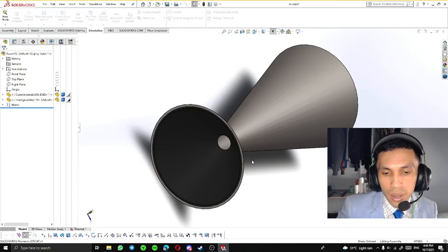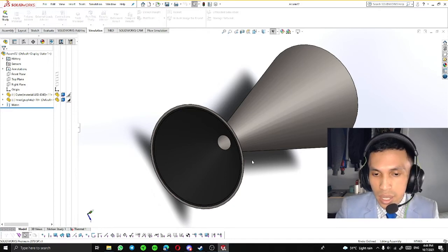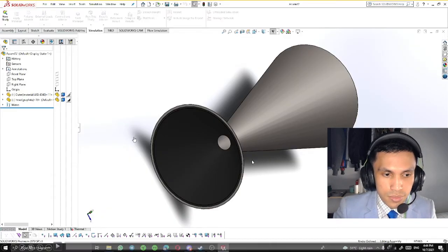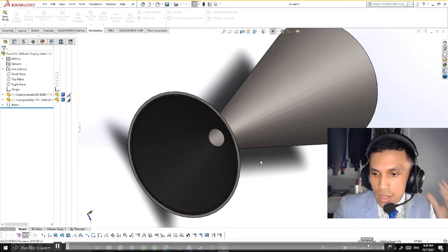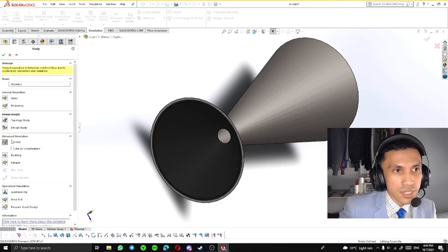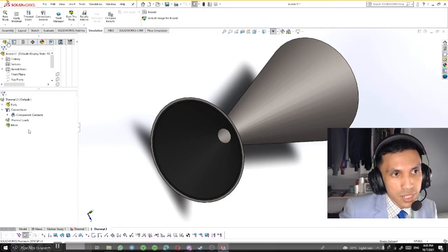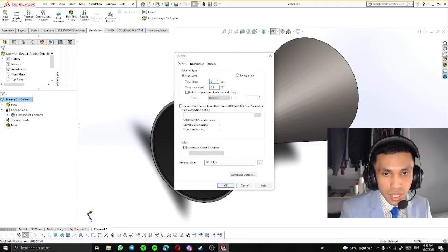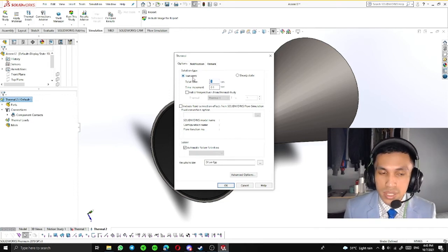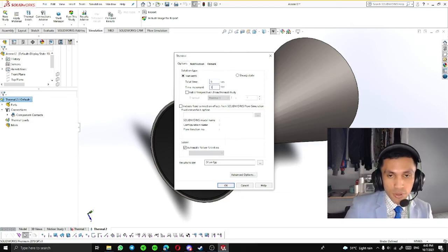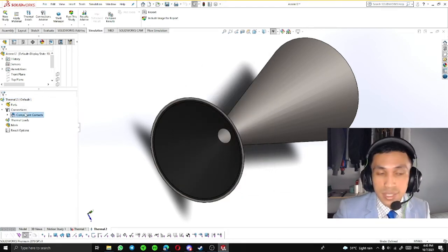Here are the simulations which I had done in SolidWorks. So here are the assembled parts for the outer casing and inner graphite. First I select to conduct the thermal study, and then set the properties to transient, because I want the result for the transient, and then set the total time for 6 seconds and the increment time for 1 second, as I mentioned before.